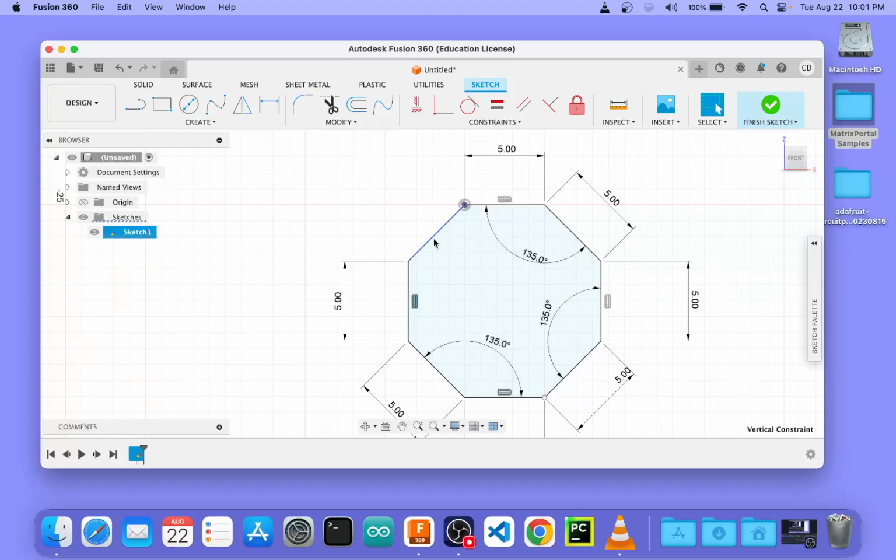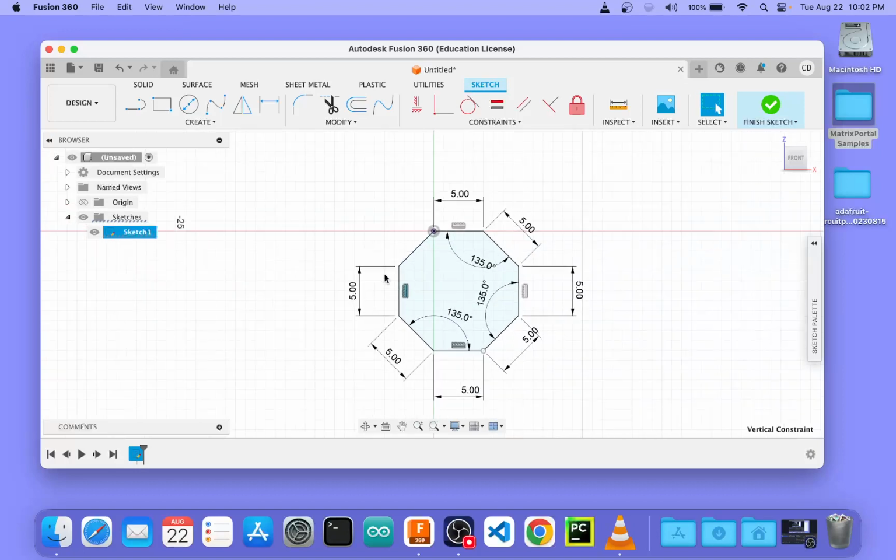If you don't 100% understand that at this point, that's not really a problem. Just know that this sketch has all of these angles sort of included in as necessary dimensions. And there's two different ways to do that. One is to enter the dimension when you're making the line. One is to make the line first and use the D key to set an additional dimension.